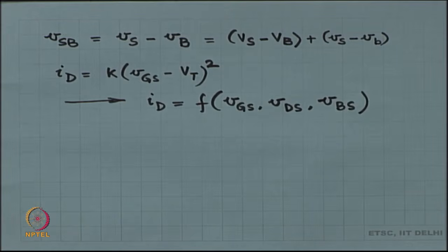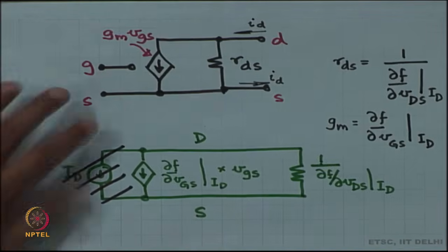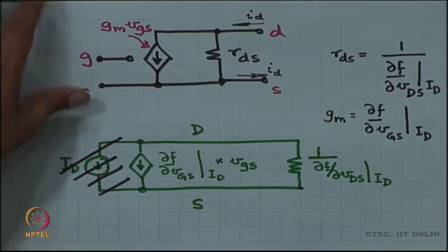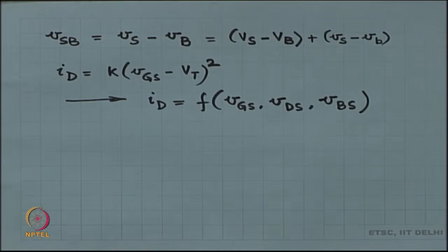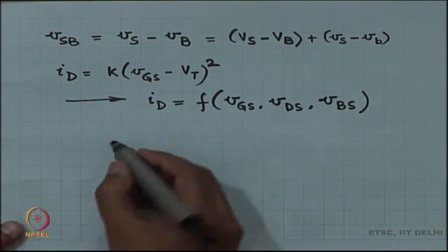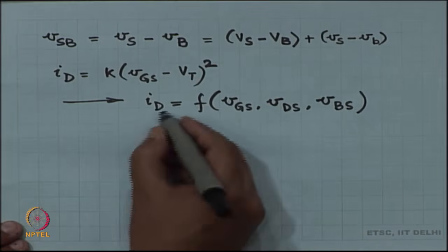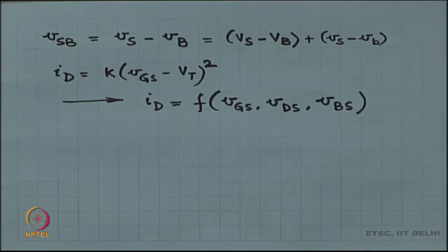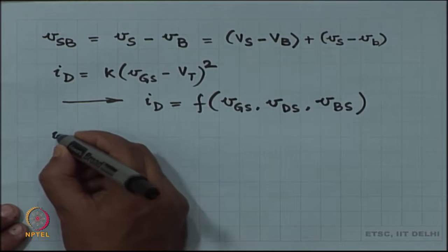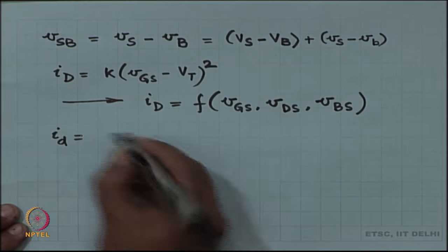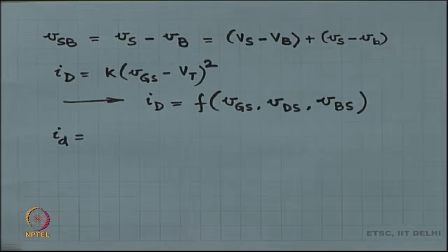Okay. So, this is the correction, and when you make a correction like this, it is going to affect the structure of the small signal model, and let us take a look at how it affects the structure. So, now Id is capital Id plus small id, right, and small id is going to be the sum of all the first order derivatives.